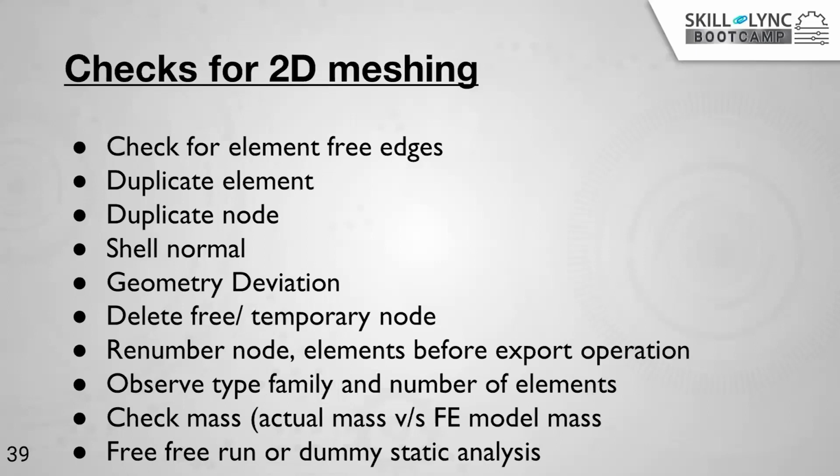Then to check if the mesh connections are proper or not, you can run a free run, meaning a modal analysis without any boundary condition, or a dummy static analysis. If there is any mesh connectivity issue, it will show up in that analysis result.